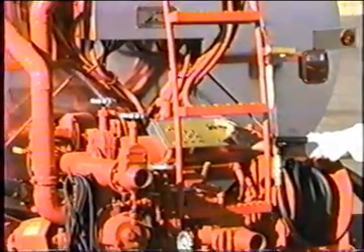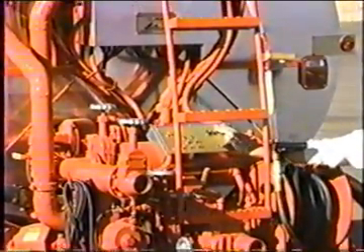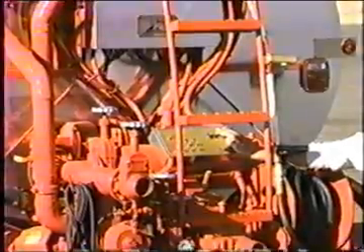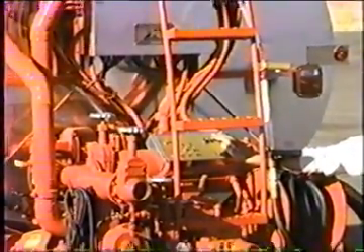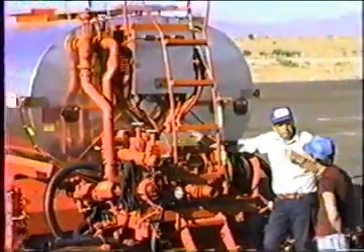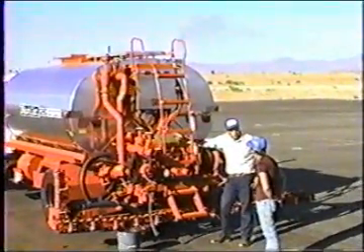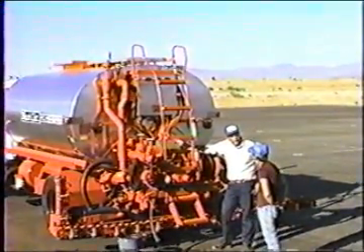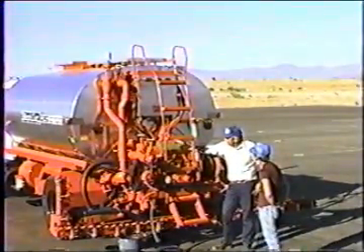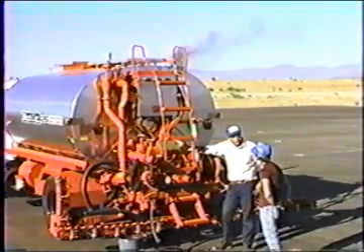Now there's times that very possibly it'll flood. It's just like your car. If it doesn't have just the right mixture when you first turn it on, you may flood it. You may give it too much fuel. And let's say we had turned it on a few times and it didn't light. To unflood it, put it in the wash position and just let it run for a while.